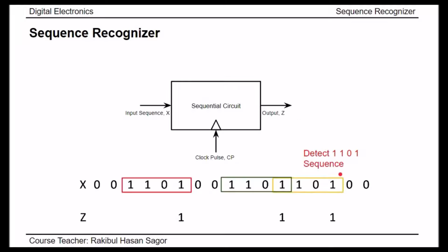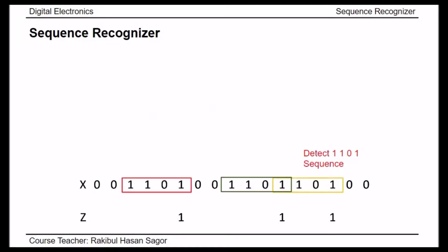So at the very beginning, we need to construct the state diagram. Let's start constructing. In this circuit design, inputs and outputs matter. For the time being, we'll assign states with some symbols. Suppose my present state or initial state is A. At the very beginning, the state is A. Now, being at A, whenever we have a 0 input, I am confirmed that I am not getting 1101, because in order to get the 1101 sequence, the first input should be 1.